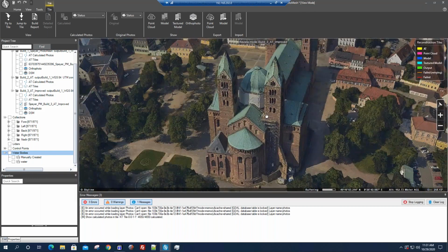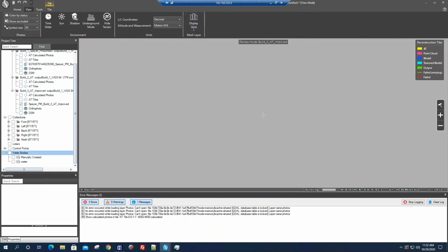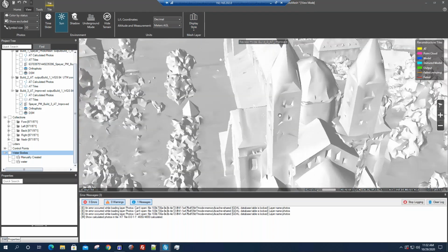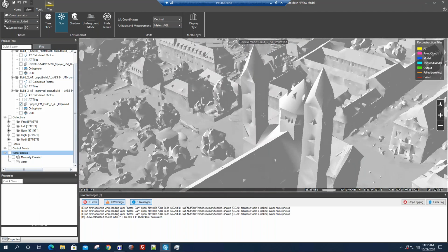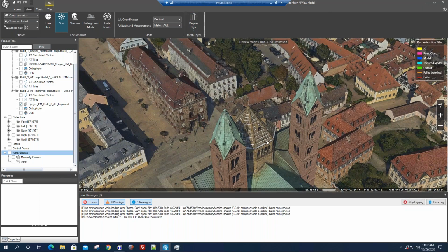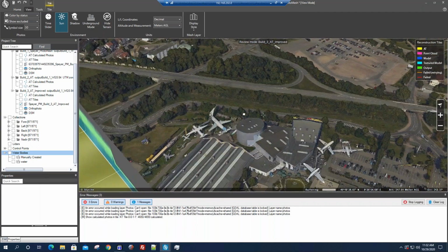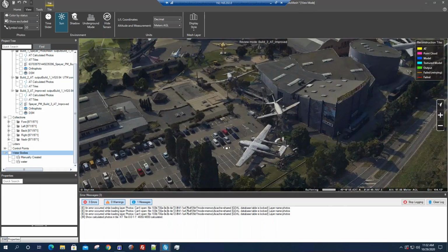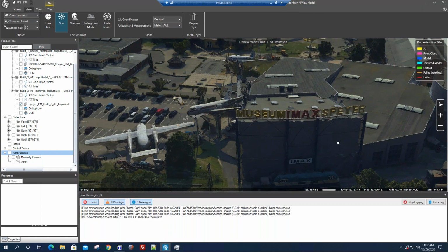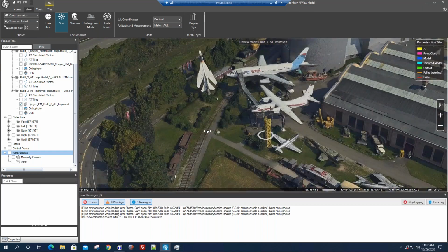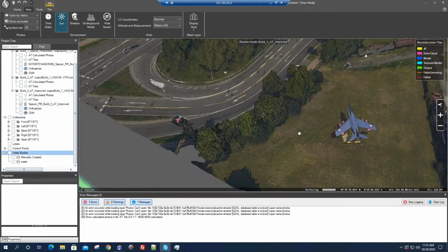Just quickly to pan around and show, one of the unique features that Photomesh has is the ability to extract edges. So we extract linear features, and you can see the linear features coming into effect in creating corners, which are pretty sharp, and roof edges. And that's part of what gets utilized in the 3D reconstruction to enhance the point cloud. So this is a very high quality aesthetic 3D model thanks to Gerhard's GGS system. And you can see with the oblique images, the ability to view things from the side gets us very high detailed outputs, and just generally a very high quality, including small cables, poles, really anything gets correlated in the 3D basis.